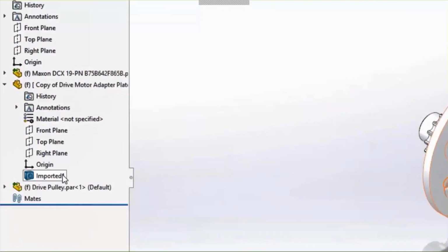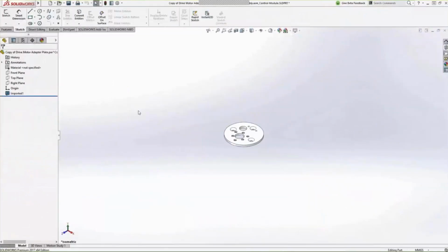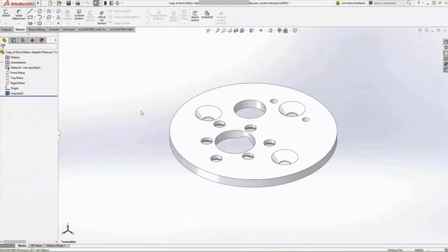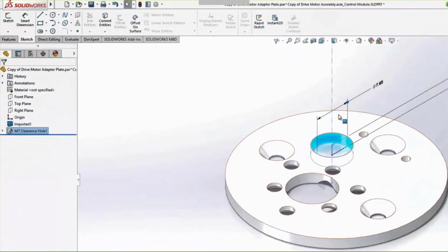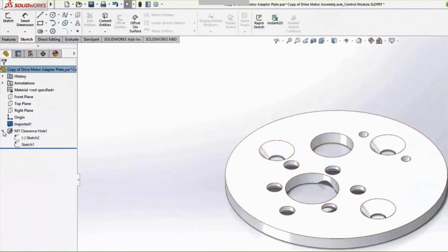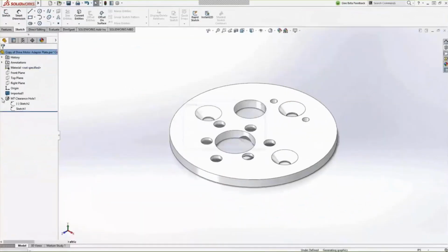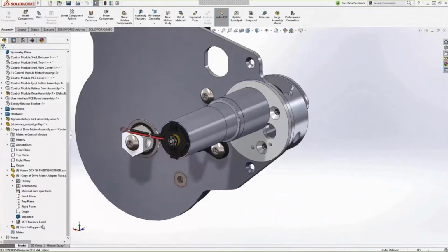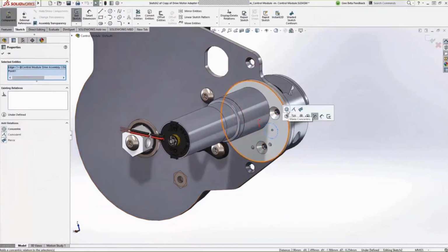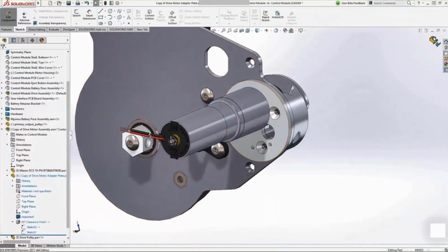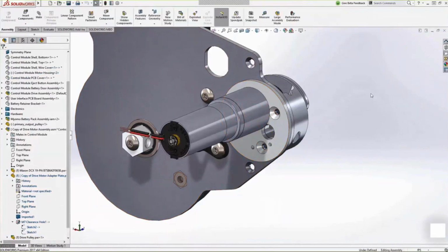Once we've broken the link, SOLIDWORKS performs the import, and we've got good high-quality geometry. It converts over our dumb solid in its own file, and now we can make our specific design changes with direct editing techniques. If we use FeatureWorks, it recognizes the hole, and it's fully editable. So if we go back to our assembly, since it's an M7 hole that it recognized, when we do an in-context edit of the position sketch, we can select other and make it concentric to our hole, moving it just slightly so that it's going to fit perfectly, which maintains our design intent.